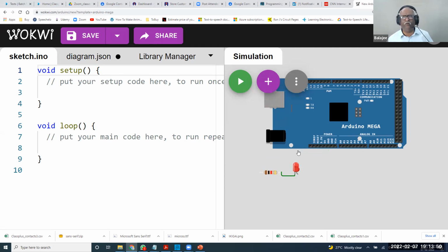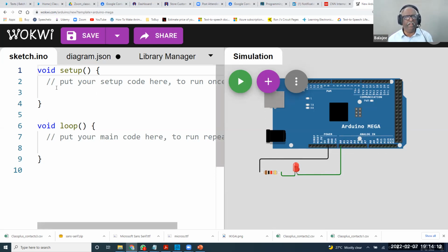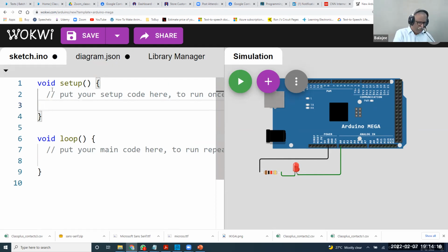If I connect it from the ground, it will become a nice black color, so you can easily understand that. Now this LED's other pin, the anode pin, I connect to the first pin, as we mentioned. Port F, first pin I'm using. Done. If I write the program here, I think you can see it. If you can't see it, let me know.